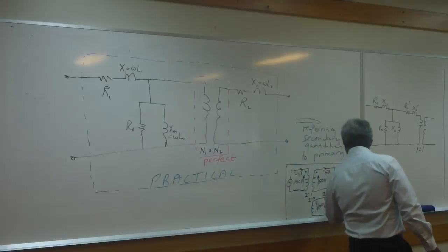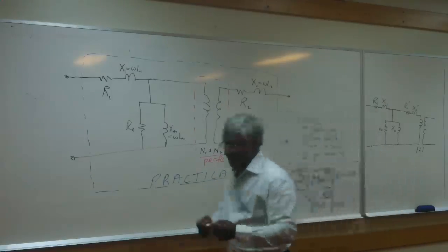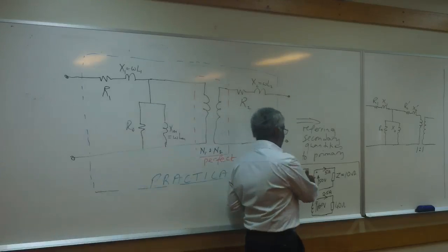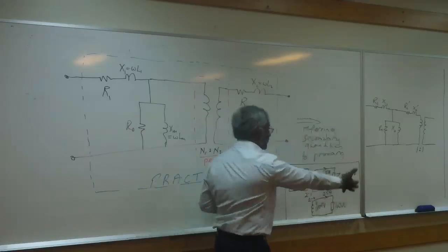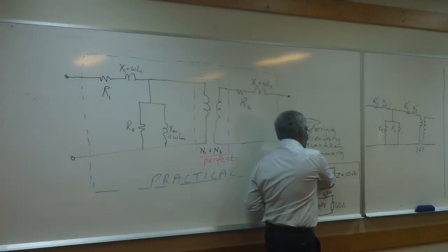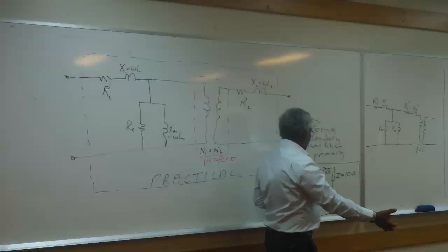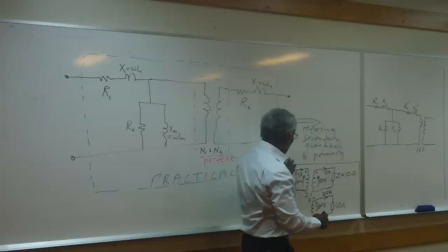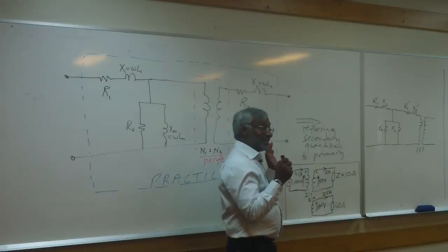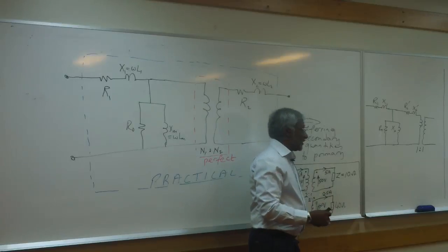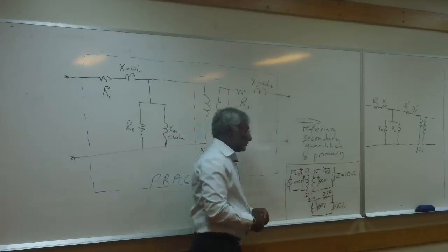So it's 40. So again, in summary, if you had a transformer that was 2 to 1, 1 being on the secondary side, and you quickly swapped the secondary side such that 2 to 1 becomes 2 to 2, and you wanted the primary not to feel anything, then in doing that you would have to change the impedance to 40 ohms in this example.